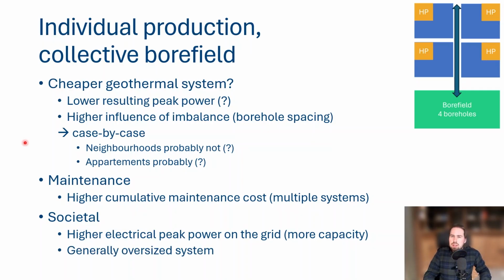And I would say that in general, this also leads to an oversized geothermal system. Because we can take some simultaneity into account if we're cautious, but there is not an easy way to do regeneration. It could be done, but it's not trivial. And secondly, we cannot be sure how our simultaneity will really behave.